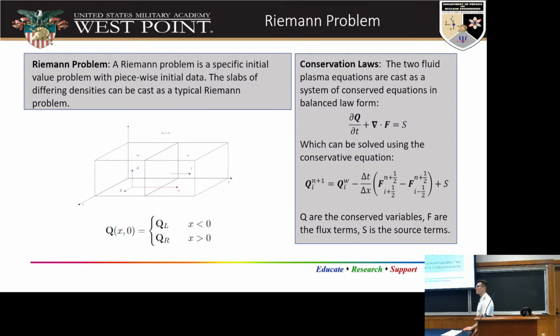So if it's kilometer size, and you're trying to propagate through it, where does the scintillation come from? So as the radio wave, this is in one dimension. Something to consider is this is in one dimension. As the radio wave propagates through that medium, the plasma is being organized in these large columns. As it propagates through the varying optical densities, the wavelength is changing as it goes in and out, and that changes the speed of the wave.